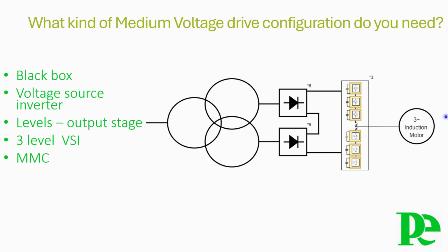Instead, we find capacitors for each power cell within the inverter part. The low voltage energy level stored in each cell results in an improved fault behavior as compared to other drive topologies. In the simplest case, such a power cell consists of 2 IGBTs and 1 capacitor bank. Medium voltage levels are obtained by adding together the outputs of multiple power cells.